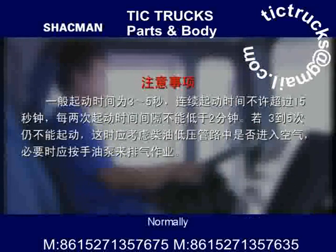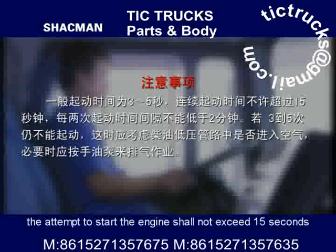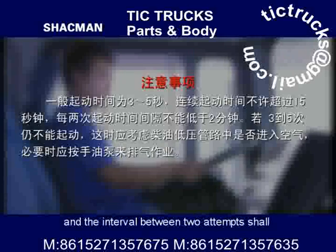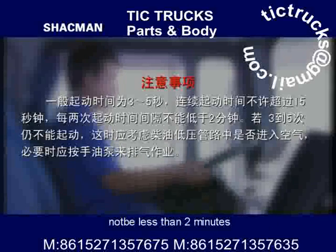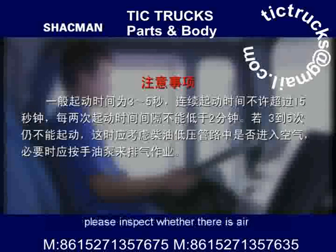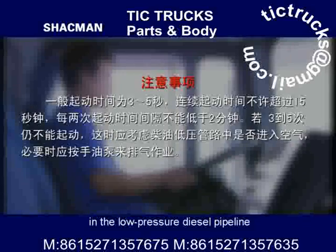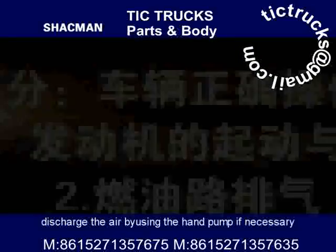Instruction: normally, the engine will be started in 3 to 5 seconds. The attempt to start the engine shall not exceed 15 seconds, and the interval between 2 attempts shall not be less than 2 minutes. If the engine can't be started after 3 to 5 attempts, please inspect whether there is air in the low-pressure diesel pipeline. Discharge the air by using the hand pump if necessary.